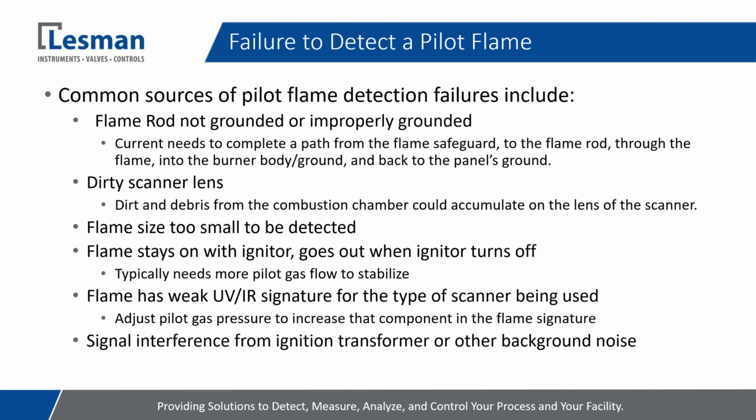Same goes where I've seen it where the flame is on with the igniter, but then as soon as the igniter turns off, the flame goes off. And again, that's just you're almost there. You just need to make a couple more tweaks to get that to latch in reliably.